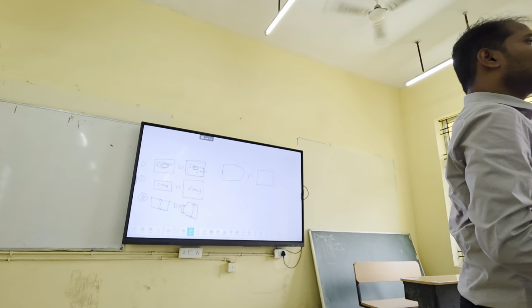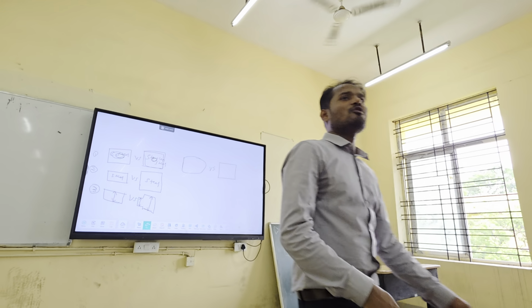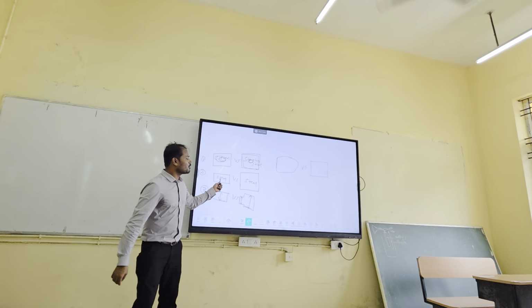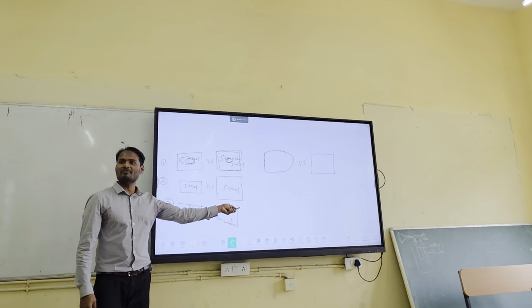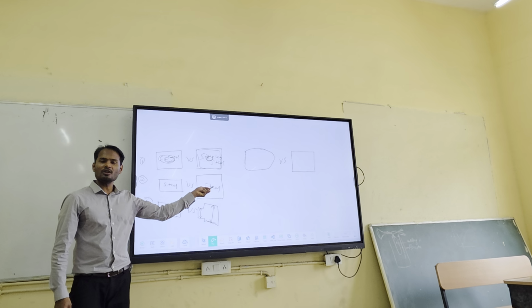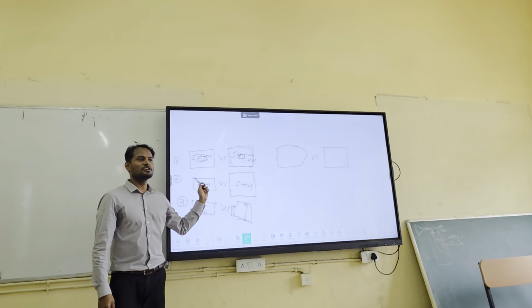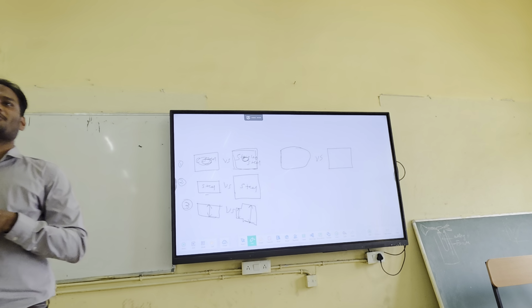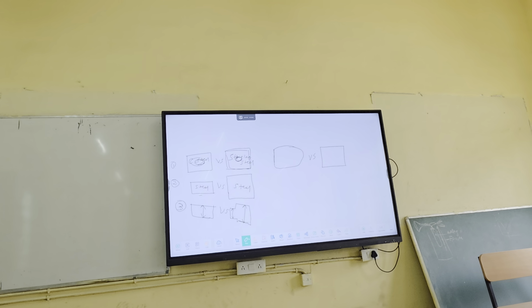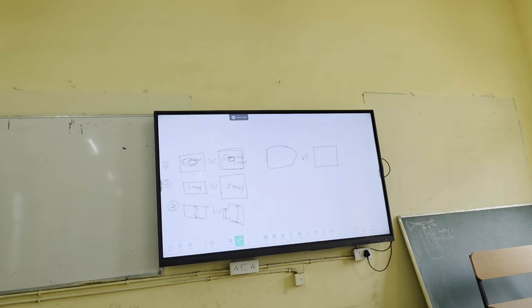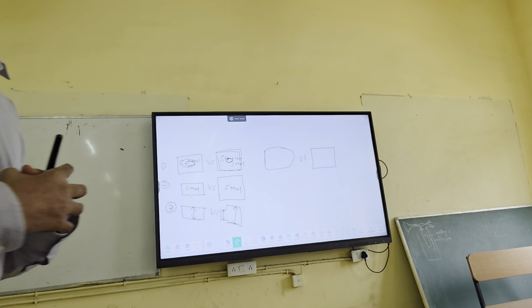Is it okay? So that is the reason actually. Now can you tell me, in this case and this case? Both are steel. But one has more cross-sectional area, the other less cross-sectional area. Or thickness is more, thickness is less. In which case do we need a higher heating rate and a slow heating rate? Okay? Right side?